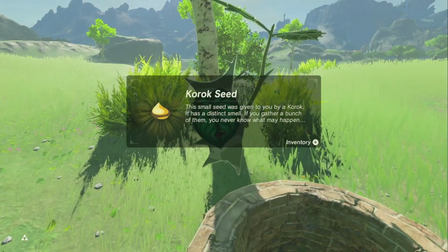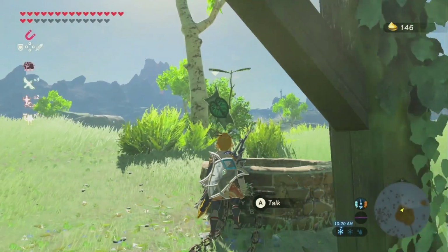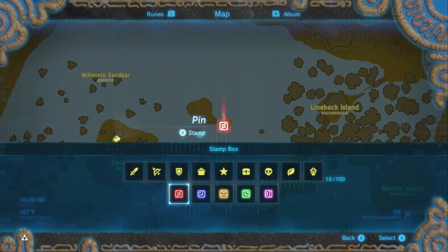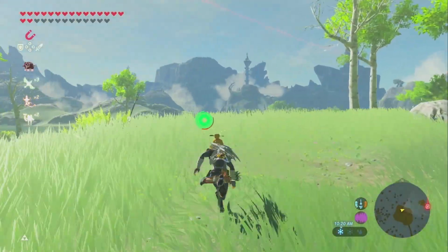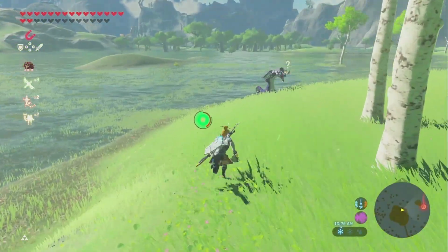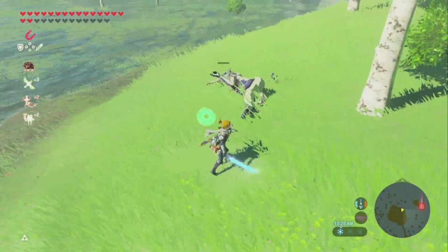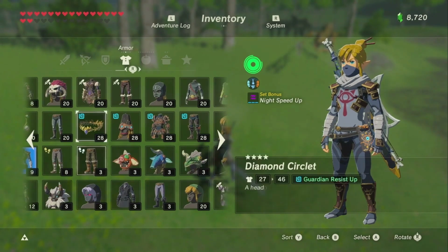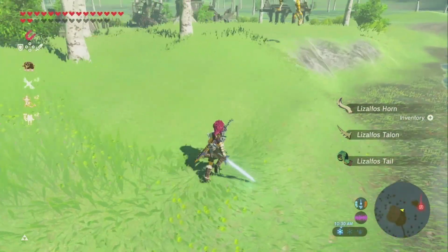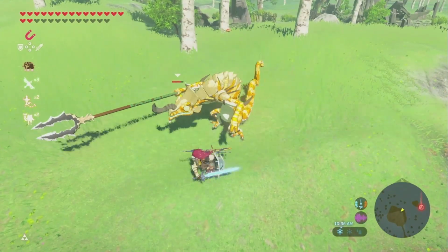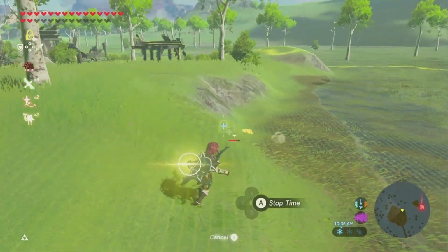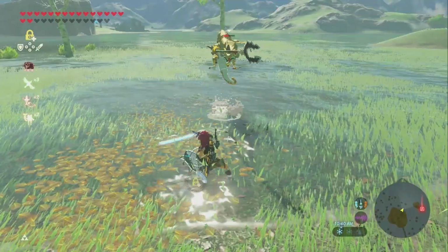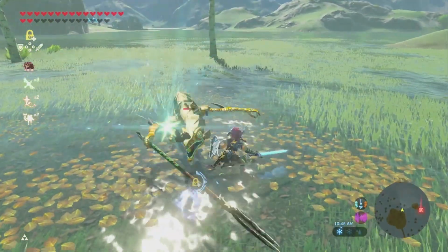Or temperature/pressure relief valves. So TPRs do two jobs. They will open and dump water out of the tank if the temperature exceeds 210 degrees Fahrenheit, 99 degrees Celsius, just below boiling. They will also open if the pressure in the tank exceeds 150 psi, the maximum normal operating pressure for a water heater. The temperature/pressure relief valve will have a BTU rating stamped on it. Its rating must be the same as or larger than the BTU rating on the water heater.